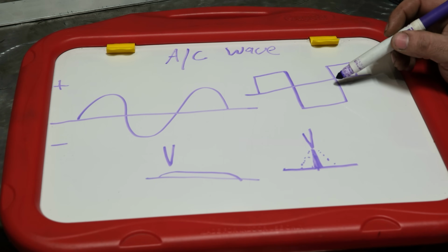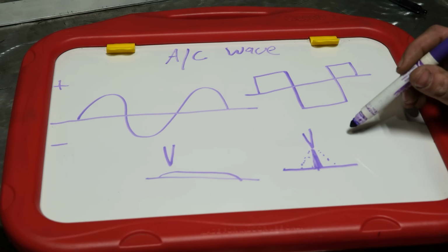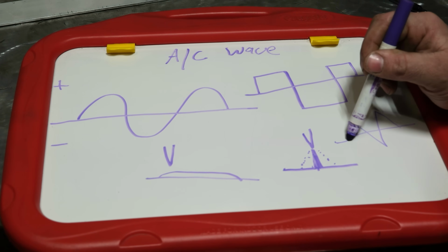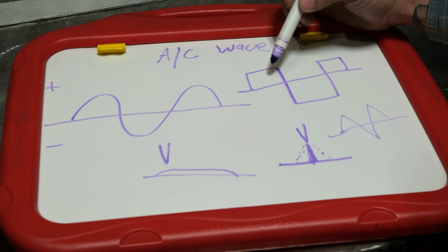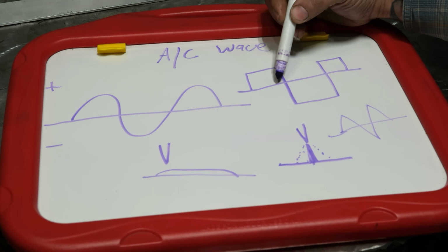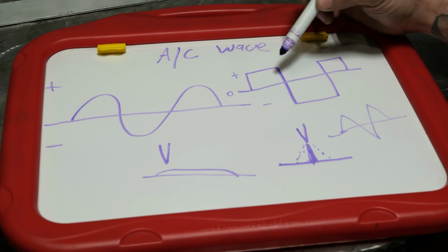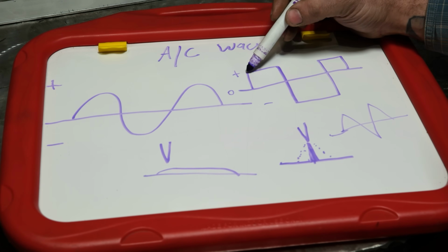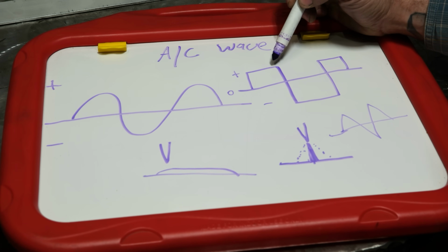Now, another way to look at all of these waves. Your machine might also have triangle wave, where it looks something like this. This is heat input, okay? So anytime it's spending right here at the 0 volts, this would be 0, this is plus, this is minus, no heat is being input into the material. Therefore, the more time that you actually spend at positive or negative voltage, the more heat input is actually going into the material.